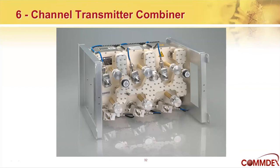They go into a common heatsink load in the back of the unit. You'll see 6 tuning knobs out on top, and then beneath the cover are the lengths of transmission line, and in the very center you'll see a 7/16 DIN connector, which is the output going to the transmitter. So this is a rack-mounted 6-channel transmitter combiner.